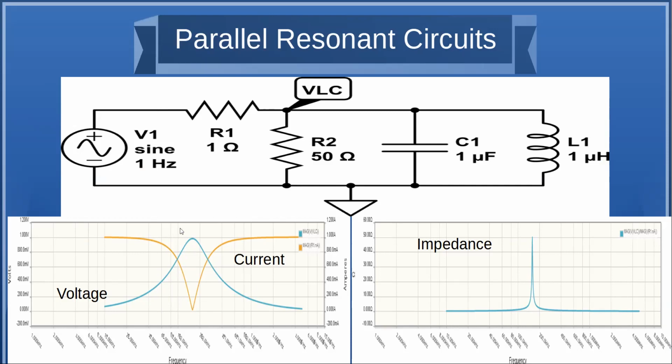The difference between a series and a parallel resonant circuit is that at resonance, the series circuit looks like a short circuit, 0 impedance. A parallel circuit at resonance looks like an open circuit or infinite impedance, which you can't ever get infinite because they're real components. This was a little calculation of how the impedance changes at that frequency. It turned out this is what we call a very high Q circuit, so it's a very narrow band where it's resonant.